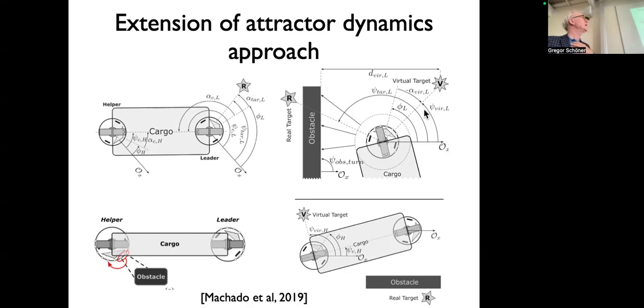They computed functions that detected situations like that, and then added a term to the equation they call a virtual target. So they put a target up here so that the robot will steer clear of this obstacle. And once you're at that target, that term goes off. Now also have a function that controls that, and then it would automatically go around that. So all of this is just done by adding contributions to the dynamics, and the contributions are erected. It's not actually neural activation. There are just some computations on the sensor data, and these computations will turn on something or turn off something, depending on the context.